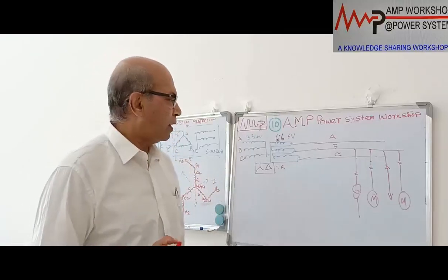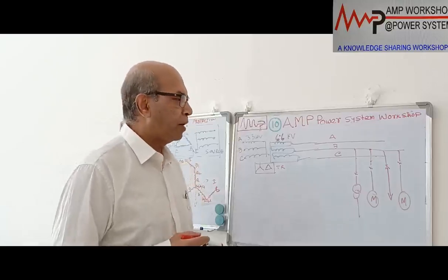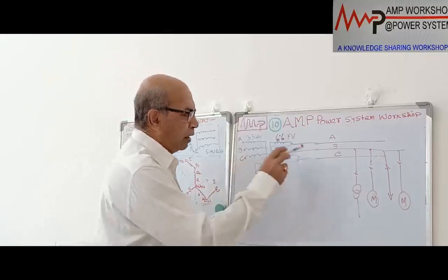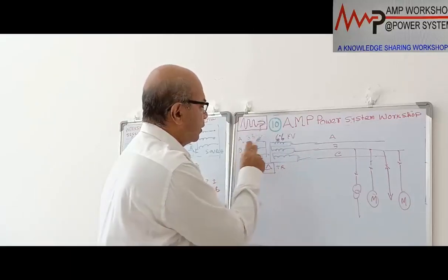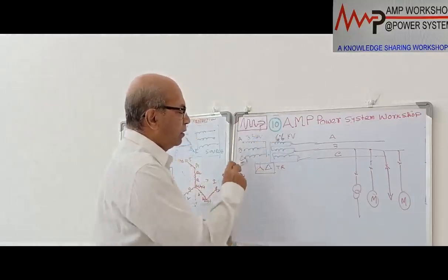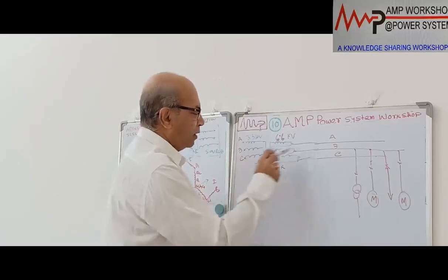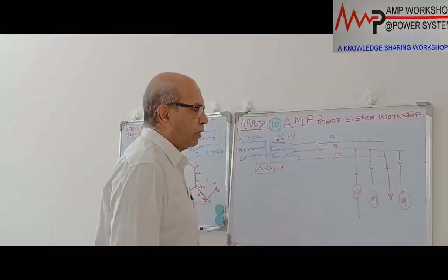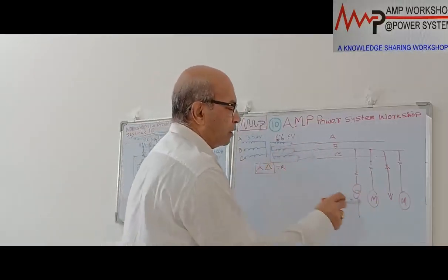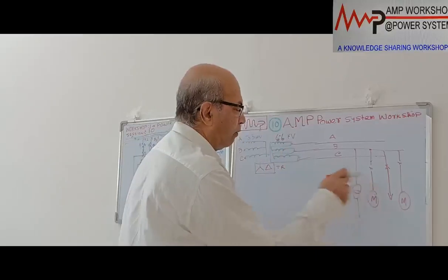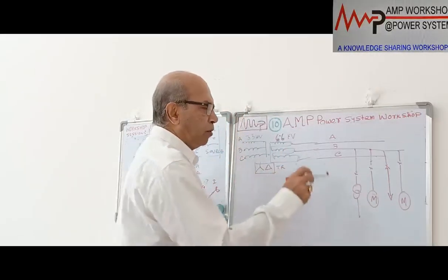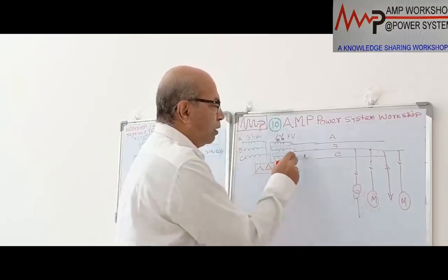So from that experience and through the process, whatever I have learned, we are trying to display it over here. I have drawn a typical delta connected system. This is a transformer 33 kV by 6.6 kV. This is a star delta transformer. The secondary side is delta, which is 6.6 kV, feeding power to the various motors. Now, due to this delta connected system, if there is an earth fault on the motor or any feeder, then automatically this earth fault will be maintained. First the earth fault will be maintained, and then this voltage will go up.